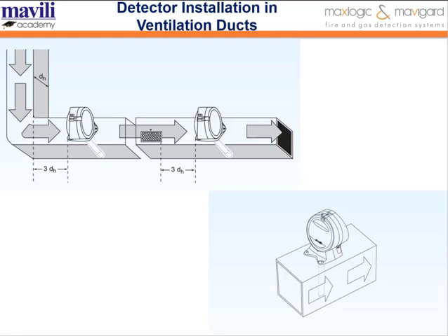These detectors are installed on the outside of the ventilation duct. Inside the detector housing, there's a smoke detector, and connected to it is a sampling pipe that extends into the duct. This pipe has small holes along its length. As air flows through the duct, a portion of that air enters the pipe through these holes and is carried out to the detector housing.